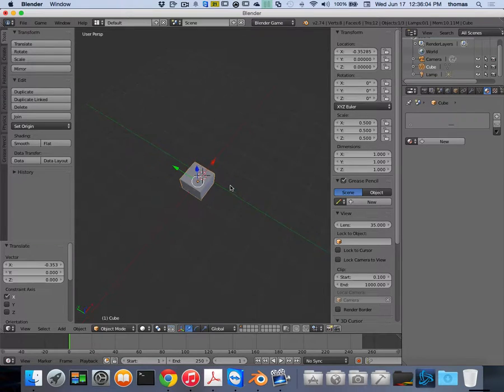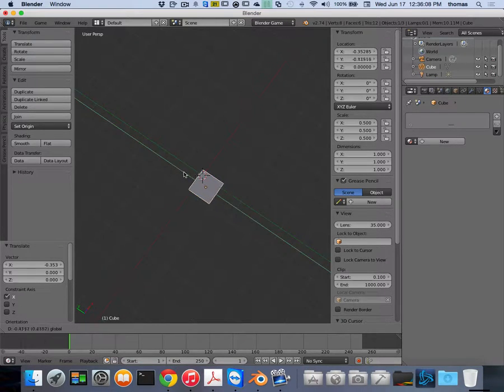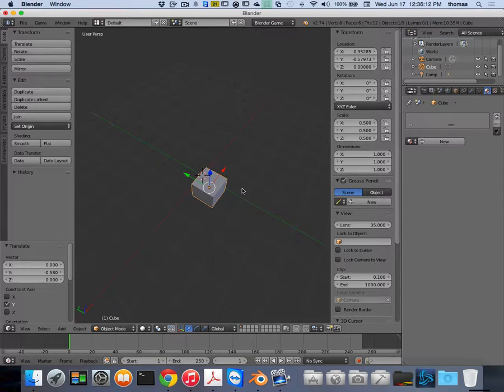And if I actually look at my grid, which is just a helpful little thing to help us, it looks almost exactly like one Blender unit. You can actually numerically position everything the way you want. So if you look up here where it says location, in your transform section of your numeric pad up here, you can transform this thing.